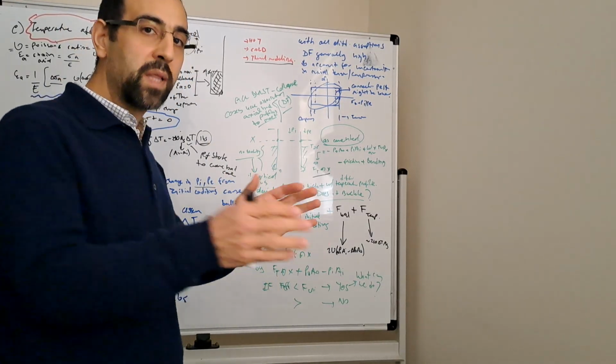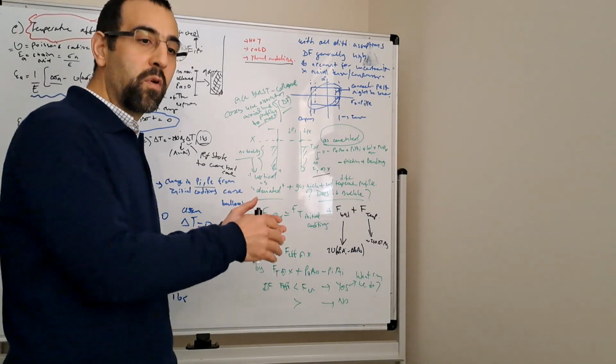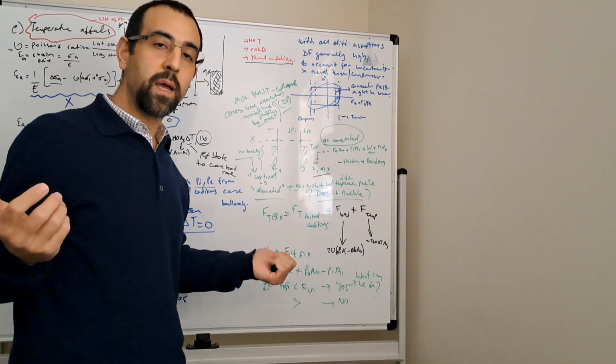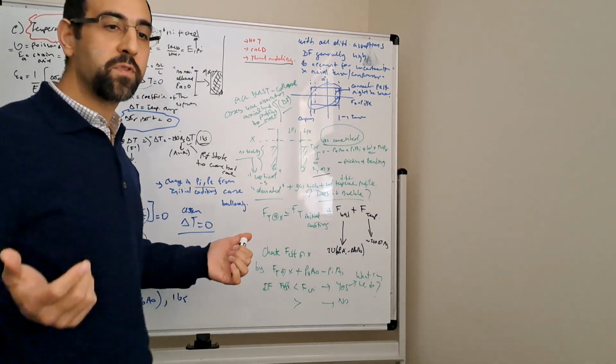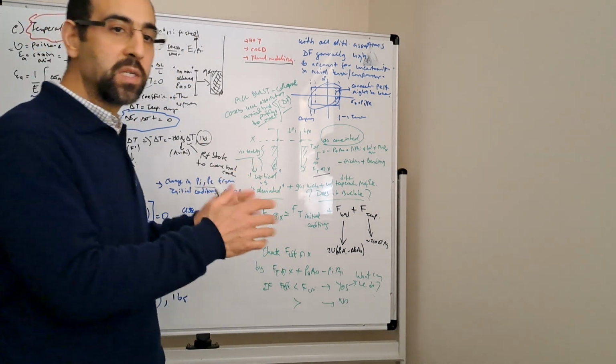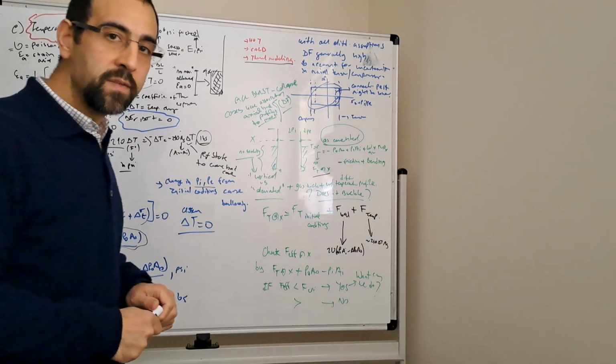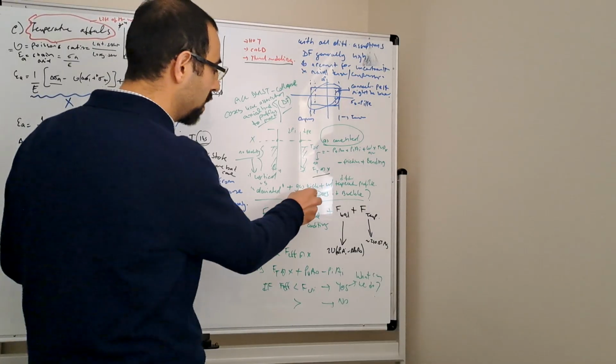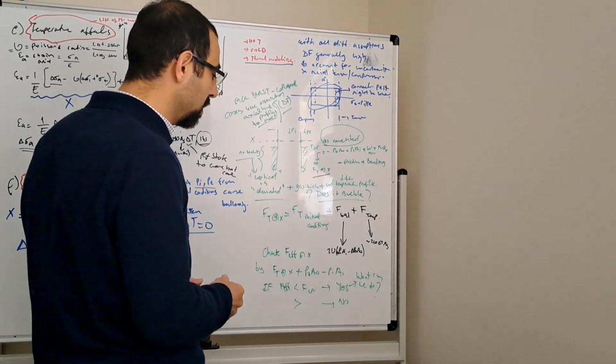Don't take the green cement test or pressure test value into this profile, because at the end of the green cement test you will basically take the pressure back, right? You will bleed off the pressure. So your locked-in pressure is the cemented tension profile. And then what happens is, let's say you are looking at a gas kick load profile.